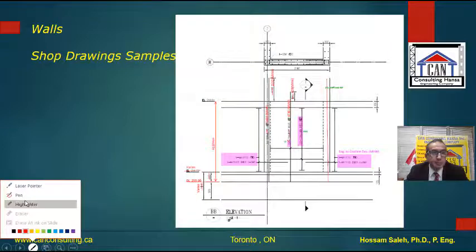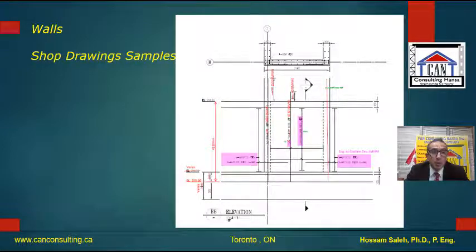So if you have here a steel bar that goes from one level to the other and stops here, and that's a slab, you should have an overlapping length, and here you can have the new bar like that. This overlapping length depends on the concrete strength and the size of the steel bar. So that's very important. Sometimes they make mistakes with that, and there are different types of that. The member can always be under compression, or it can be under tension. So if you have a tensile force, then you will need a longer overlapping length.